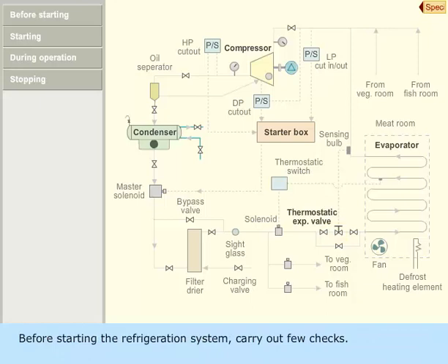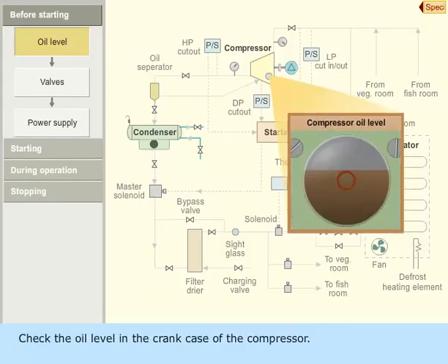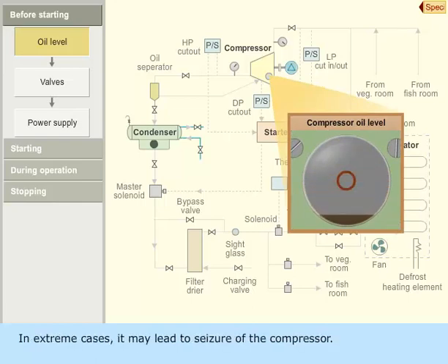Before starting the refrigeration system, carry out few checks. Check the oil level in the crankcase of the compressor. Insufficient oil wears down the components. In extreme cases, it may lead to seizure of the compressor.